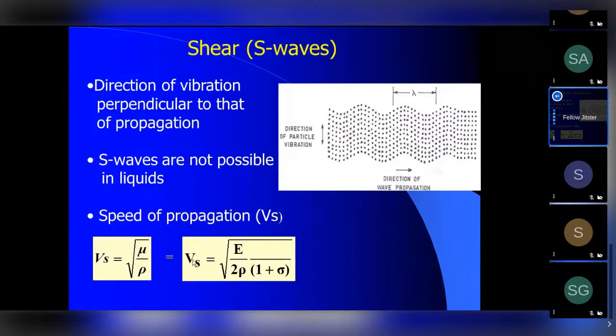So here the bottom is again defined. How do you calculate the velocity of shear wave? The velocity of shear wave is a function of the rigidity modulus and the density, or the shear wave velocity is a function of the Young's modulus, the Poisson's ratio, and the density. So anytime you get the velocities of a rock down within the earth, you are going to find out parameters of its rigidity modulus, the Young's modulus, and the Poisson's ratio, which speaks a lot about its properties. We are interested in the properties. That's the whole purpose.